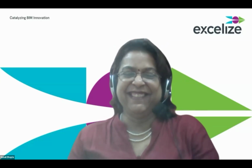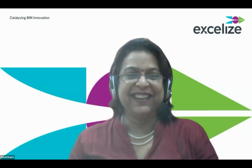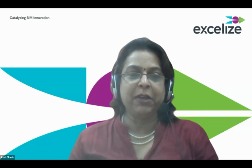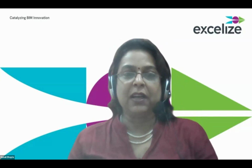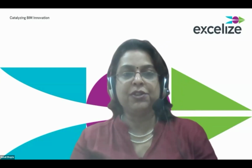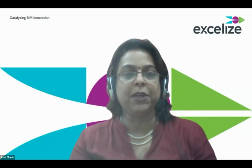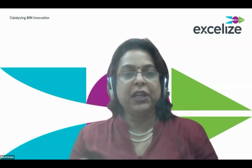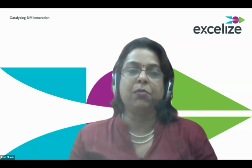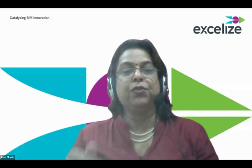Sonali is asking that ELV and IT systems come very late in the design process, so does it make sense to go for BIM for these systems? Yeah, you should not be coming in late. What we always tell all our clients is that everything in your project should come in when the coordination is happening. Because when your ELV comes in late, you are just working around what you are given, and your system might not be the most efficient one. So you need to come in along with all the other consultants at the same time.